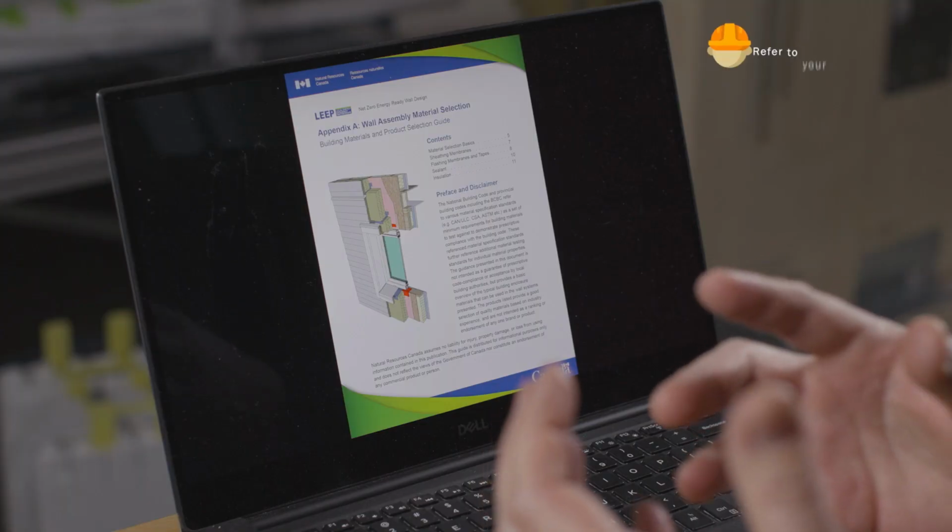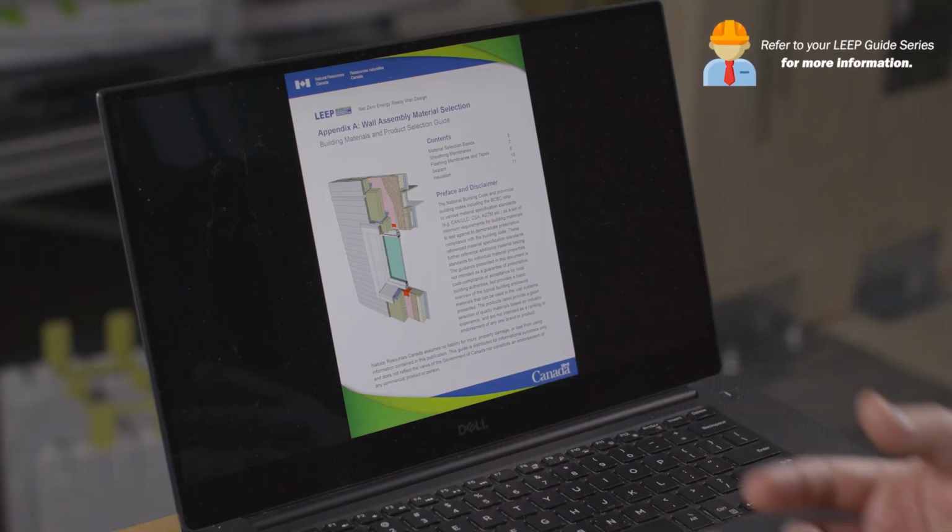Okay? So when you look at materials under the building code, we are governed by a number of standards. When we're selecting appropriate materials for air barriers or insulation or sealants or tapes, it's important they do their function. Air barrier materials need to stick to each other, and they may be from different suppliers or different manufacturers. And so it's critical to pick sealants and tapes and membranes and things that are all compatible and are going to stick and last the life of the building.